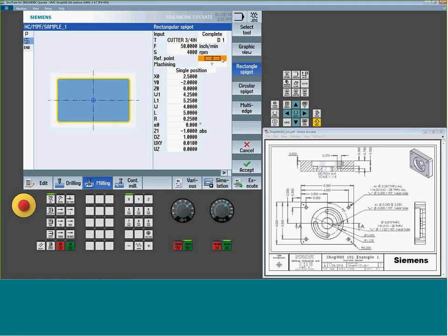Okay. Feed rate, again, just like we showed, feed per tooth, feed per minute, same thing with RPM, toggle between them. Now the reference point we didn't have to do in the facing side, what we do here, and this really has to do with the datum location. Where do I want that to be relative to?